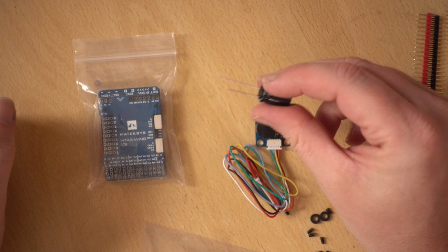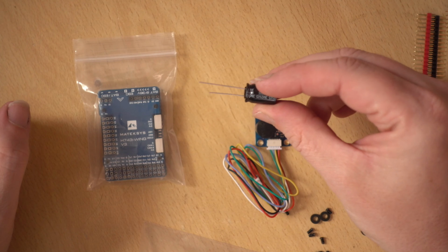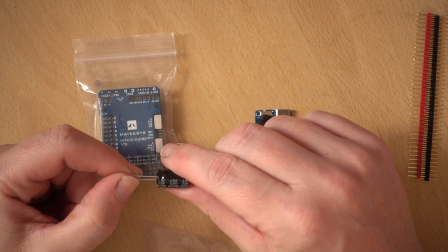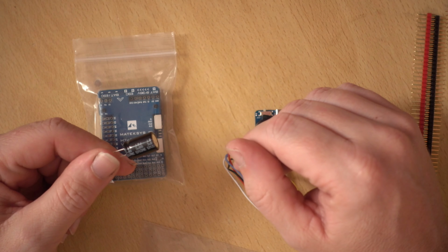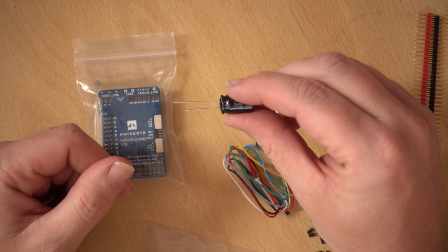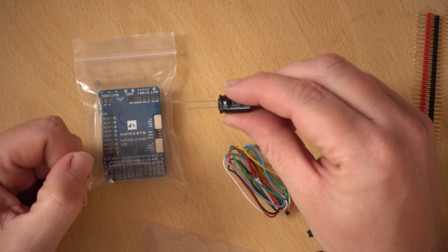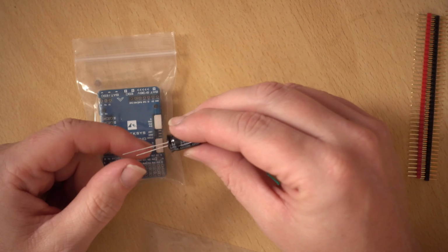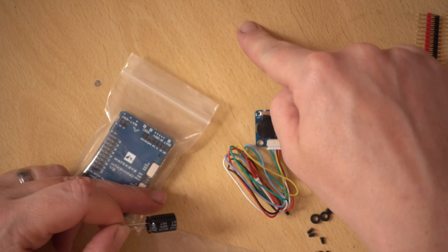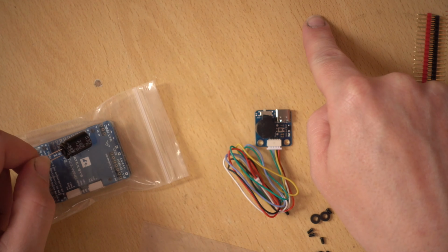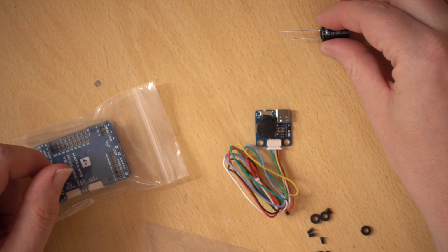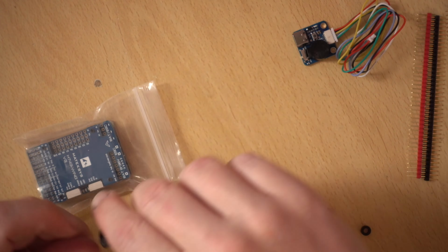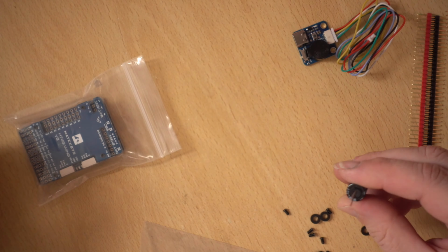And the reason for that is it is better on the ESC. The idea with capacitors in a noise prevention role is the closer it is to the thing that generates the noise, the better job it will do. So if you've got your ESC over here and your flight controller here, with the capacitor, we'll pretend that's the ESC just to make the visual a bit better.